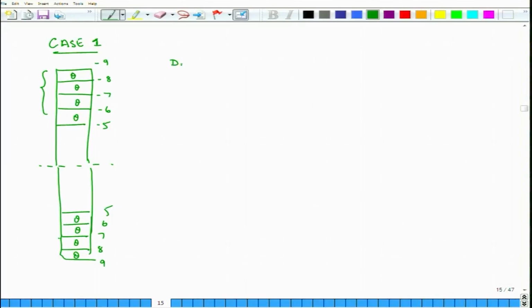All the middle layers are going to contribute nothing, because all these are 0 degree, okay. So, what will be the value of D16? D16 will be Q16 bar times 1/3, and you can consider these 4 layers as one fat layer.